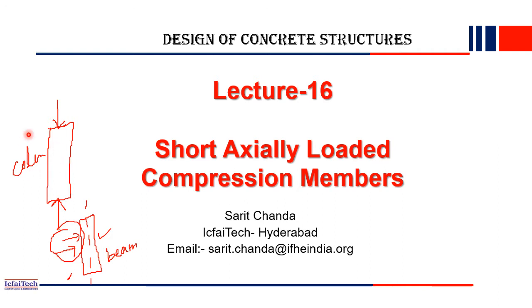Again, based on the loading pattern we have seen there are three types of columns. One is the axially loaded column: if the load is acting axially to the column, then we call it an axially loaded column. If the load is acting eccentrically about one axis, then we call it a uniaxial bending column. And when the eccentricity is about both axes, x and y, then we call it a biaxial bending column.